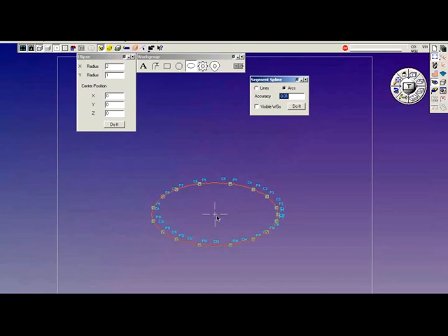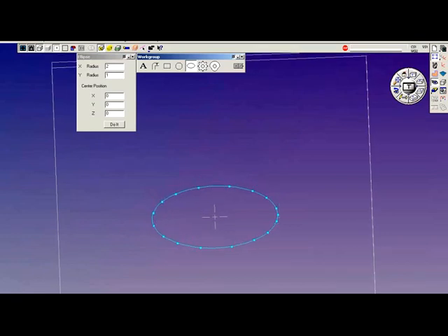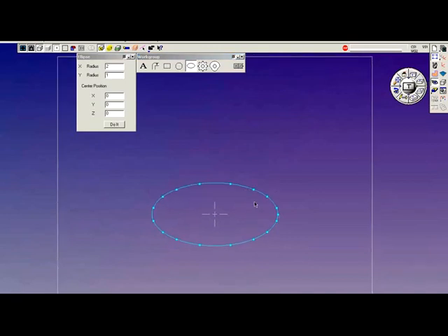This will generate a lot less G-code, a tremendous amount less G-code, and give us G2 or G3 moves, depending on the direction of our cut. So this is handy for minimizing the amount of code going out to your machine. Doesn't alter the shape, it simply converts it from B-spline to analytic geometry.